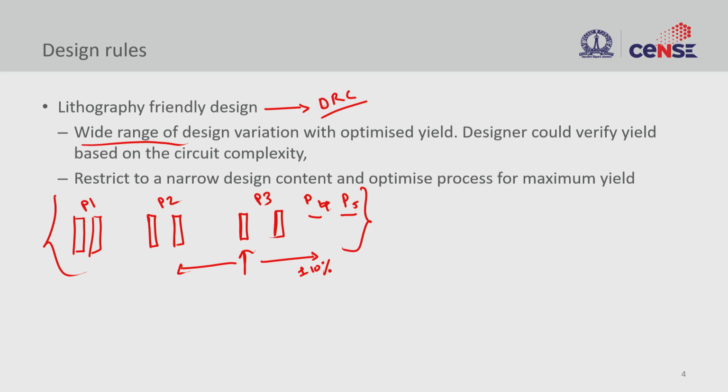So that is very important when your design has multiple variation, and also if the lithography process tells you that you can print all these different variation, then you should be a little more cautious about what is the yield on each of this design or each of this pitch, right. If they are suboptimal, then you may want to rethink about your complexity.